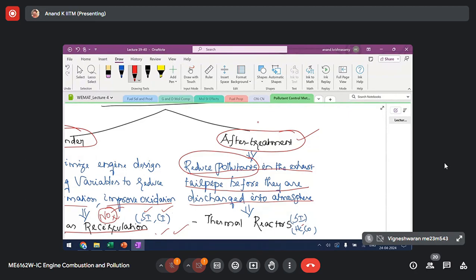Dual fuel means both the fuels are being used simultaneously in each combustion cycle, whereas biofuel is either this or that fuel. Yeah, that is a flexi fuel. You can design an engine in such a way that you will be able to run with different fuels, but that fuel alone will be used at once, as the sole fuel.